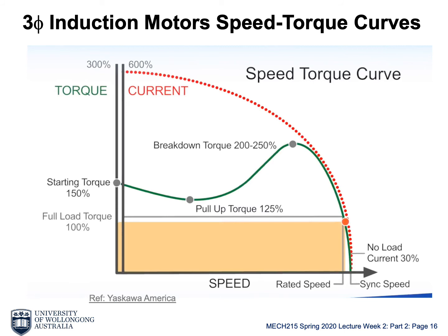So first, let's look at the torque. For our conveyor, the torque of the load is a constant. We can consider it roughly as a constant. So the requirement is that our torque from the motor needs to always be larger than this payload torque. Otherwise, when it reaches a certain point where the payload is larger than the motor torque, the motor cannot speed up and reach our rated speed.